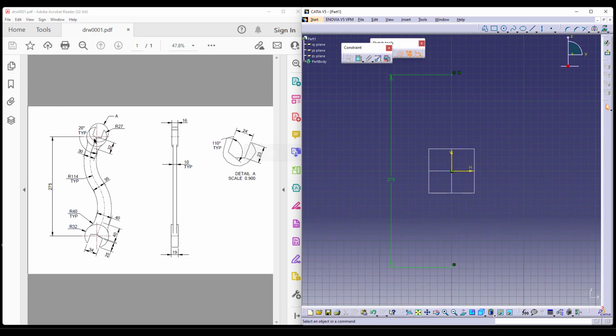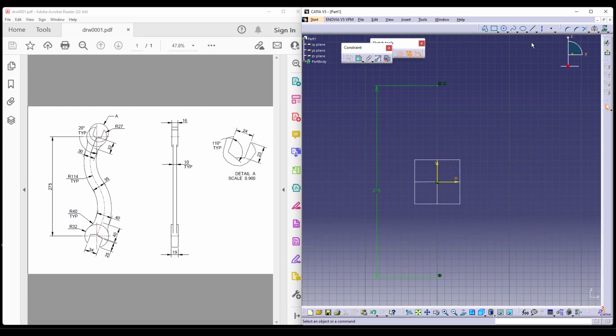Now, from here there are a few sketch elements. Let's begin making one after the other. There is a straight line this way. The angle from here to here is 20, which they have already given. And since that is TYP, the bottom side is also 20, as in this angle is also 20. And the depth of this is 32.